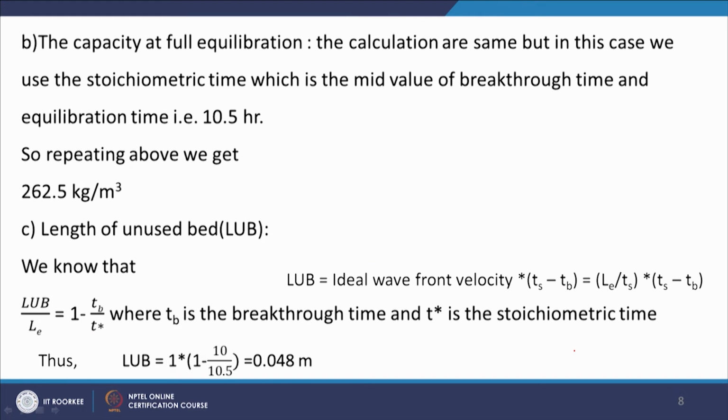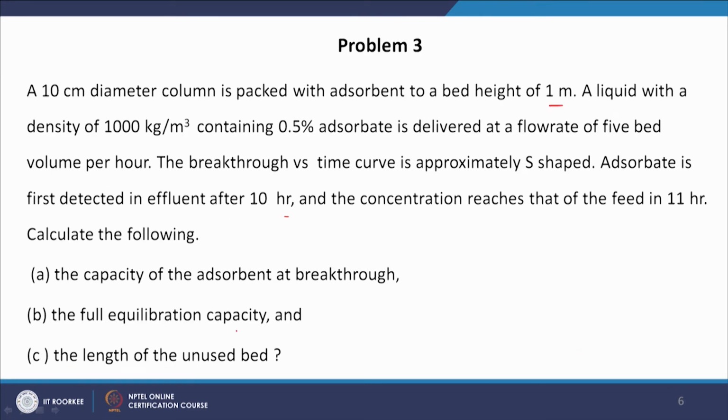Then second part is the full equilibrium capacity. Here adsorbate is first detected in effluent after 10 hours. So, this is our breakthrough, and concentration reaches that of the feed in 11 hour.